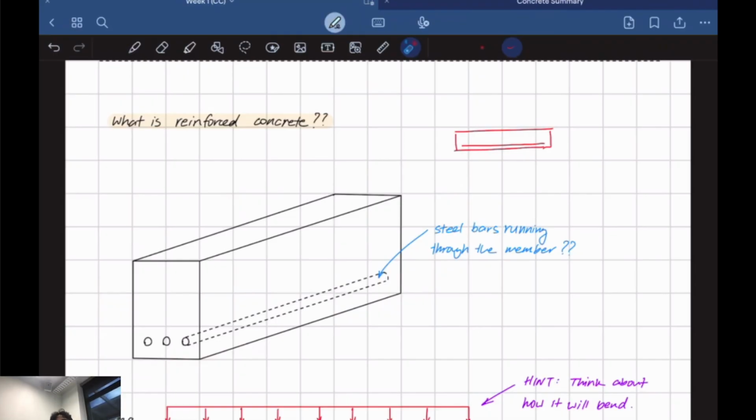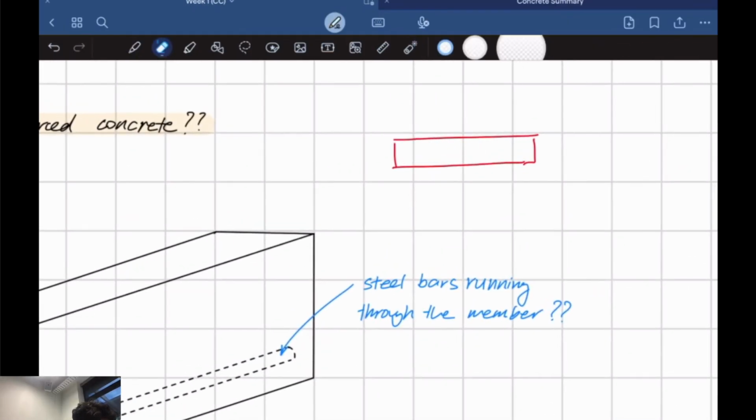Does anyone know why we put steel in the concrete? Is it to support the different type of pressure that concrete itself is under, because in one direction the steel helps support it? Yeah, essentially. So pretty much concrete is pretty strong in compression. However, in tension, it's pretty weak, right? It's going to crack quite a lot. So let's say for this beam here, I've got some sort of UDL acting at the top. If you think about the way it's going to bend, like this.